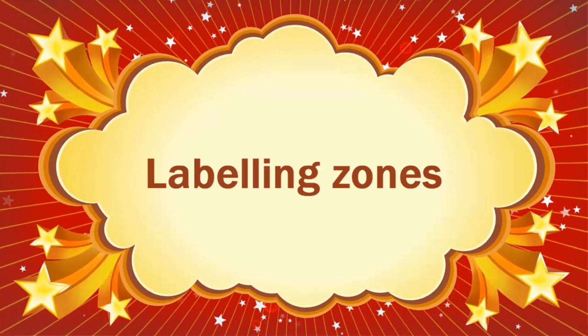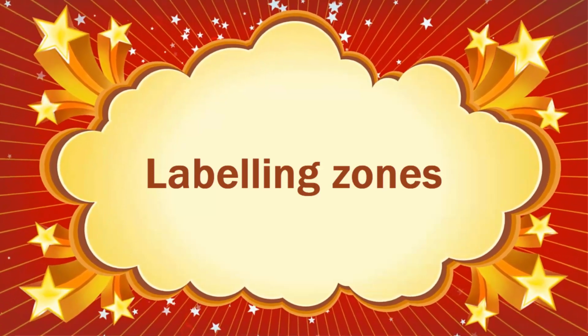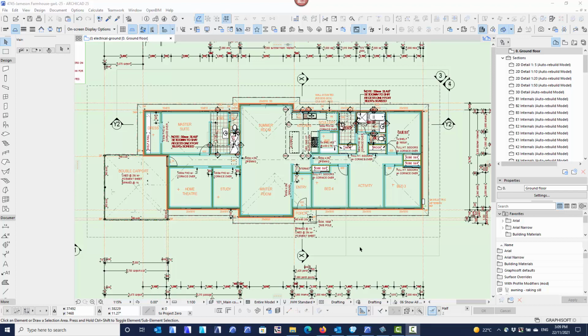This is a detailed look at using the label tool with zones, which is something we can now do in ArchiCAD version 25 from build 4013 onwards. Prior to that, we could only ever use zone stamps with a zone, which has its drawbacks because you can only have a single zone stamp associated to a zone, which means that you can only have a zone stamp in one layer. If you want multiple room names, for example, on the floor plan and the electrical plan, you would have to place multiple zones in different layers.